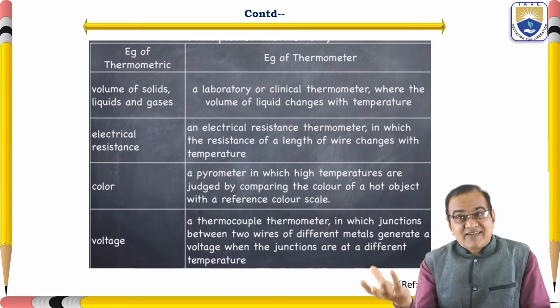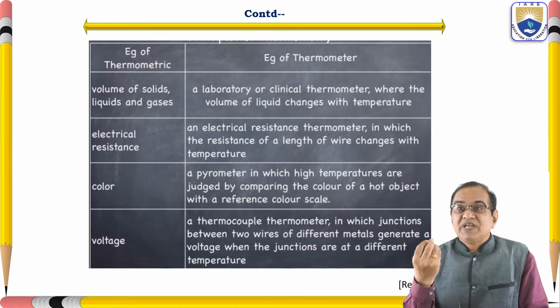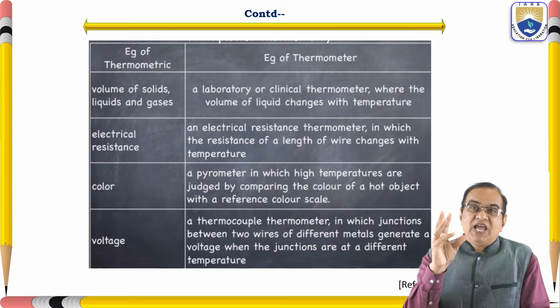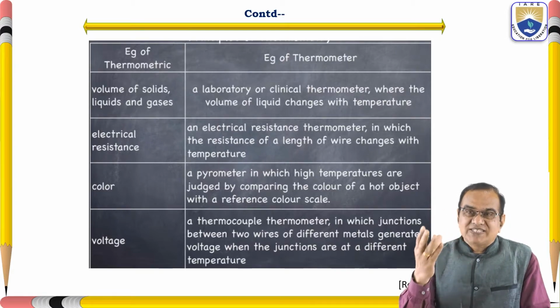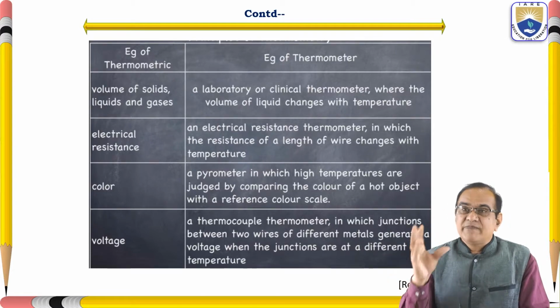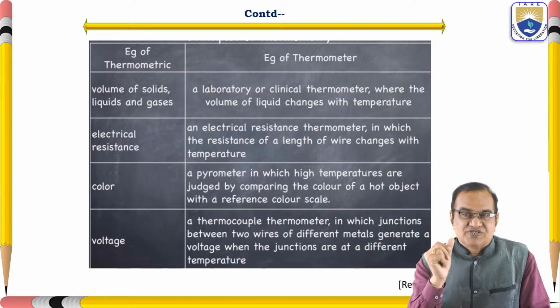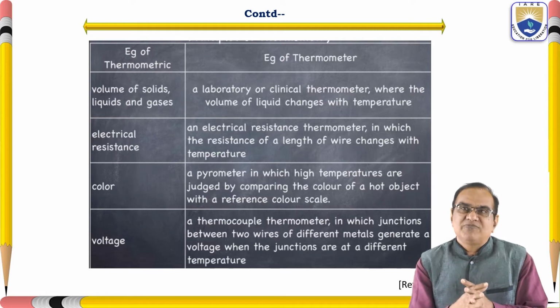But if there is more gas inside the cylinder, the flame is very dark blue initially, and slowly, by the last day of emptying the cylinder, your flame will be somewhat yellowish. So you can find out from there also.